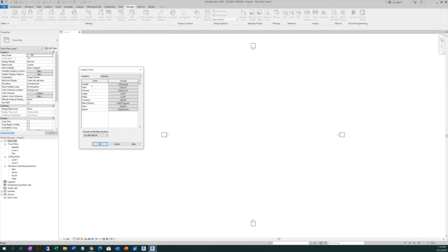If you have imperial units, you don't have to do this. However, I need to check the email that Julio sent us in order to establish the imperial units, okay? So in the case that you have metric units for the length, click on that, then you see units, millimeters, you click on that, and you are going to select feet and fractional inches.